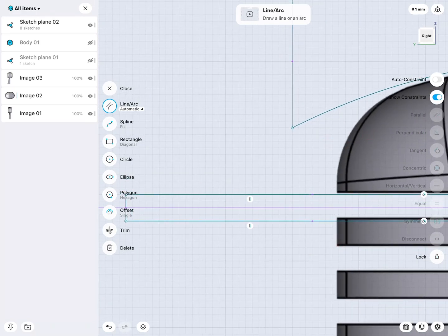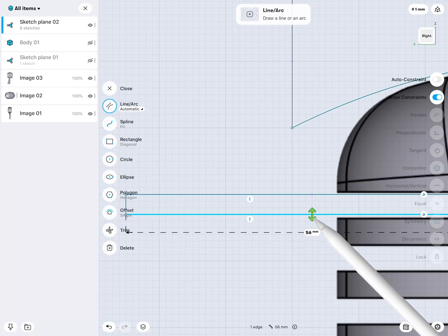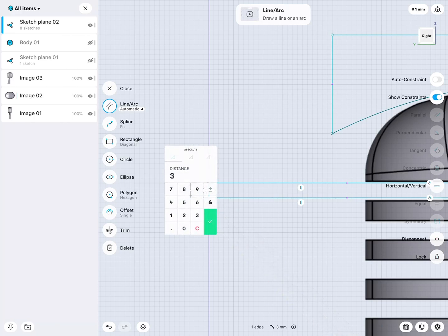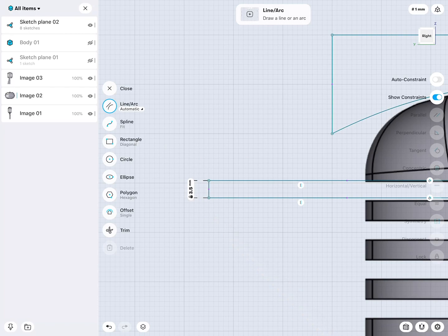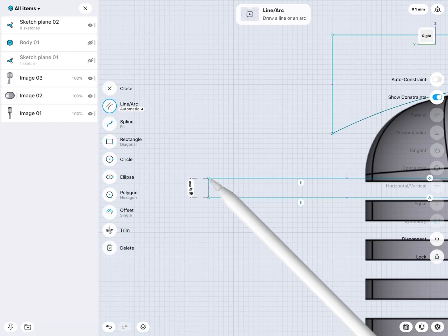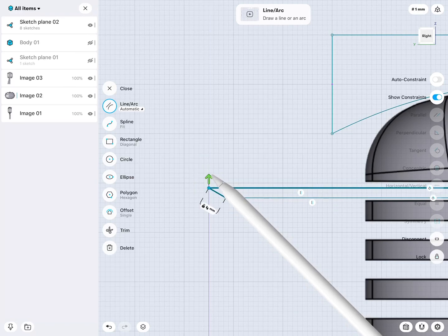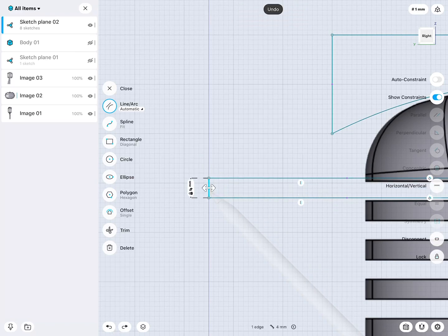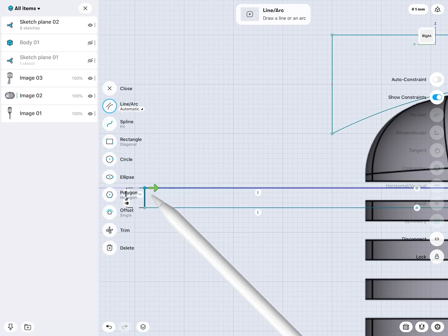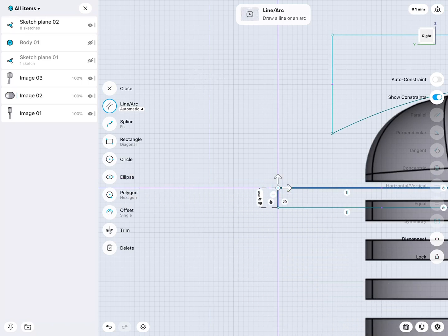Okay. This can go up one more. This is maybe too much. Let's take a look. 3 millimeters. Let's set this to 3.5. I like working cleanly with the grid, so I will set this to 4 millimeters. This edge I would like to be vertical. So now when I move the sketch, you see it updates the way I want.